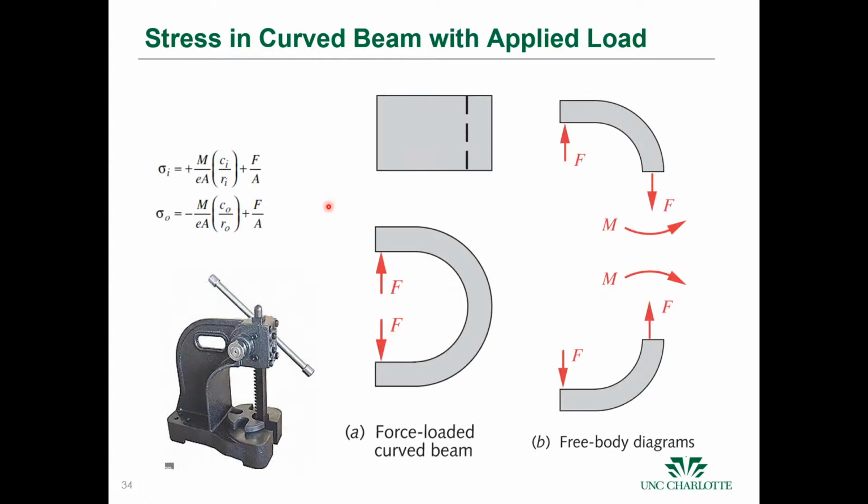So stress in curved beams shows up on a lot of elements, such as our arbor press here, which is used to press bearings and shafts, or press things out of press fits. And in this case, we often have an applied load. So this is an example where you have a force-loaded curved beam, and in this case you have this additional force that you need to deal with.